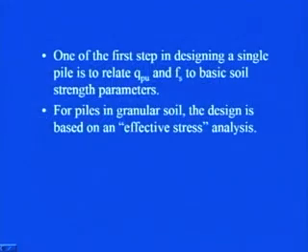So, we have to relate first of all the unit point bearing and unit skin friction to basic soil strength parameters. For piles in granular soil, the design is based on an effective stress analysis. So, let us say that a pile is being driven or bored in granular soil. In that case, c is equal to 0, that is, cohesion will be 0.